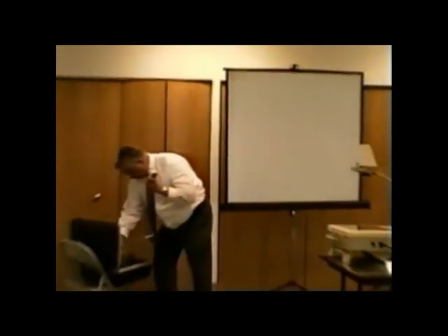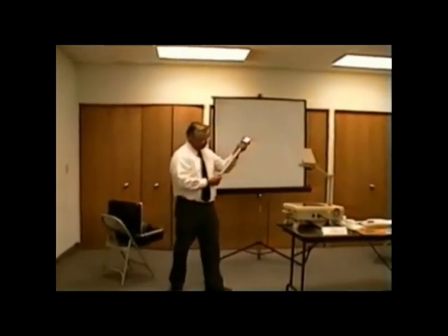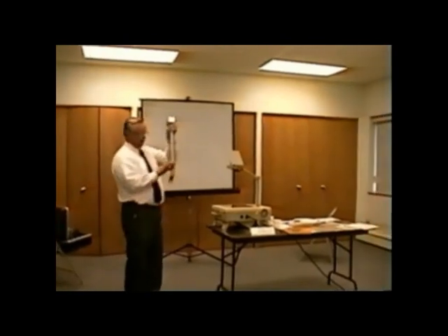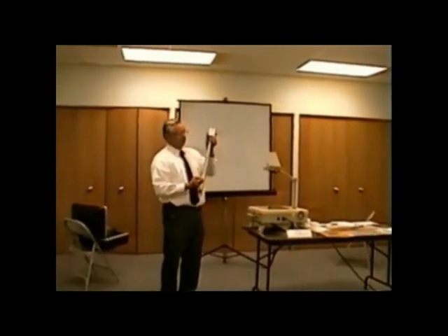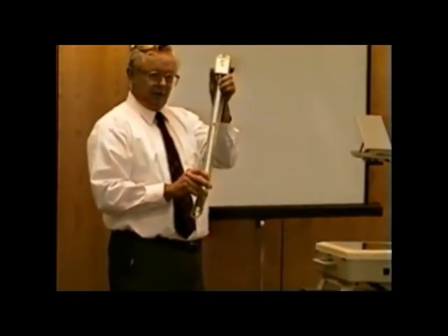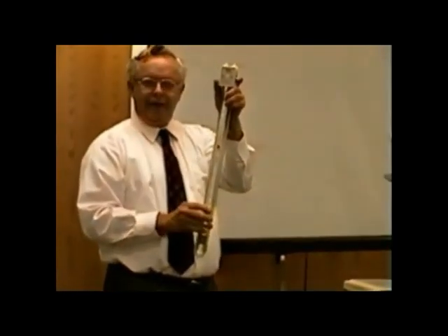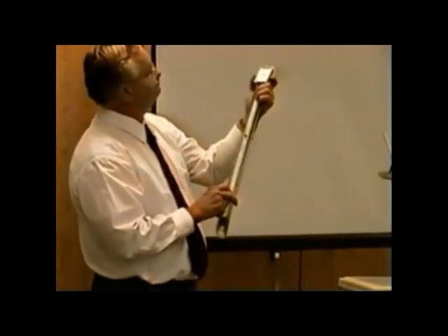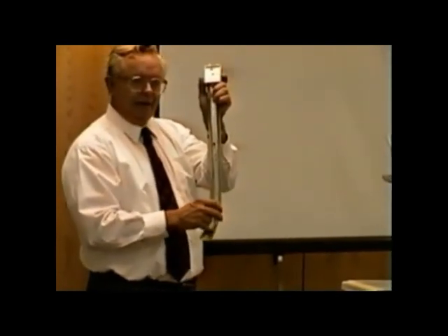You can take a slack tube manometer made by Dwyer. It's got green-colored water. It is not antifreeze, ladies and gentlemen. We check gas pressure in inches of water column, not in inches of antifreeze. So green-colored water does evaporate out of the plastic. Okay? It's a nice instrument, very accurate.